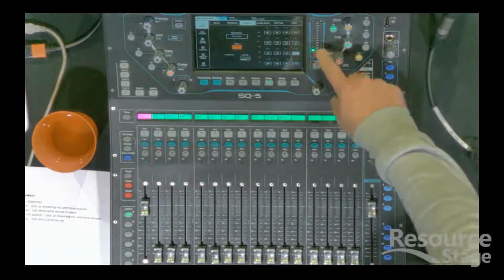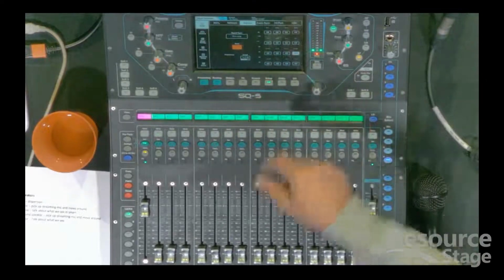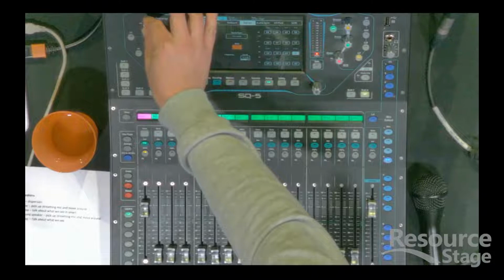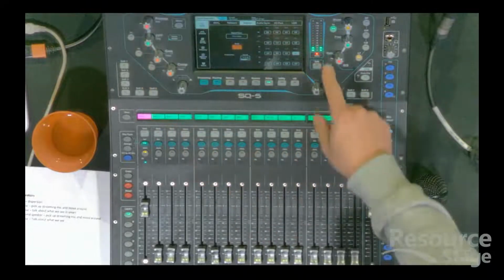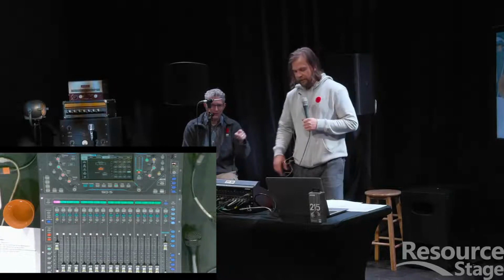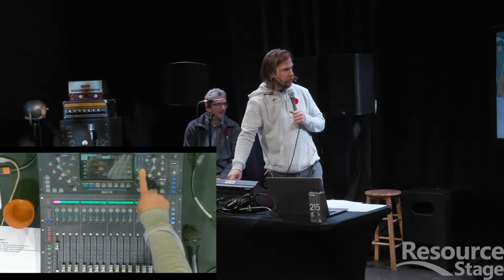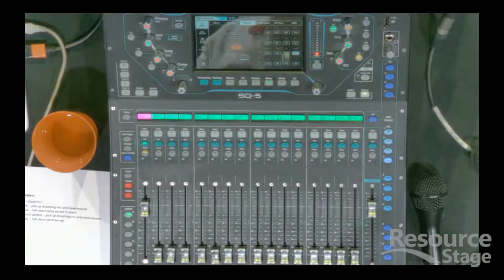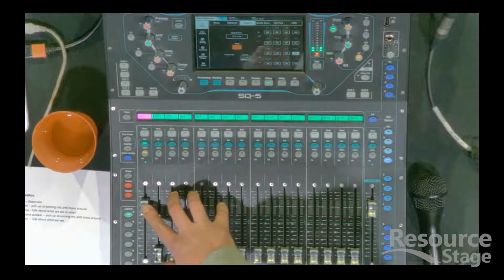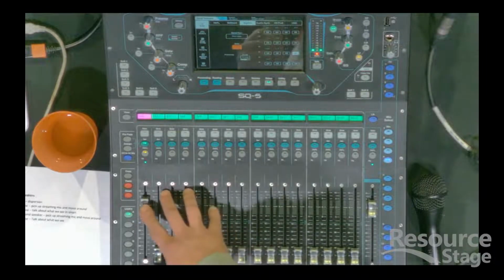So we can see here on my meter, here's where I'm going to set my gain, or I'll use this meter to set my gain. So if I set that, so I'm getting approximately nominal level coming into the console. And we know that because when Paul was setting it up there, he pressed the PFL button, which showed the input level on that meter that he's talking about. Yes, thank you. Yes, I did brush right past that. Set my PFL. So now this meter is metering my microphone. And I'm getting a pretty healthy signal there. And what that means is that when my fader is at 0, I have room to come down, and room to come up, and room to mix this microphone in context of everything else.